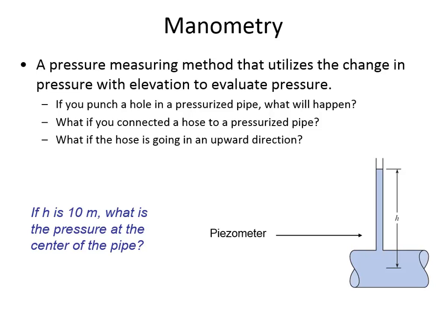So that tells us it's going to be more than 50 meters. Anybody pop those numbers into your calculator and find out what exactly? 50.968 meters. So 50 meters, that's like half a football field, is how tall the pipe would have to be coming out of the ground in order to measure the water pressure with a piezometer.